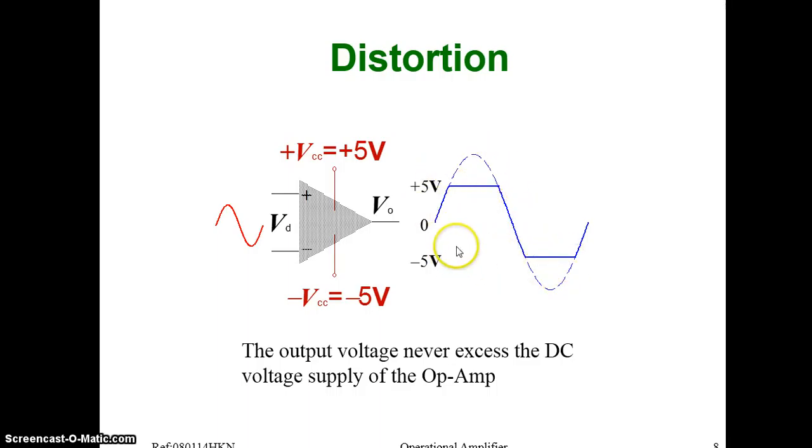That is the reason when we did the differential amplifier in the lab, I told you to give the input voltage of the differential amplifier in the millivolt range. If you give a high voltage, when it is amplified, surely the transistor can go to the saturation level and your output will be clipped.